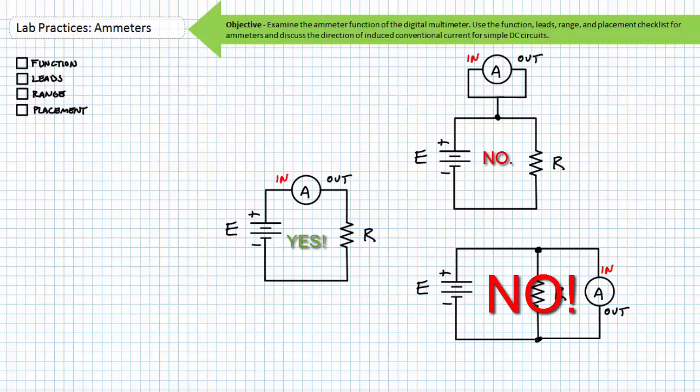The ammeter correctly inserted in series with the device of interest displays a current value in amps, and the sign of this current value indicates direction. Again, I'm framing this entire lecture series around conventional current, where conventional current is assumed to travel from the positive lead of a voltage source to the negative lead. Electron flow theory, the actual direction of moving electrons, is opposite of this, but the accepted convention since 1752 is positive to negative. Who am I to argue against such established precedent?